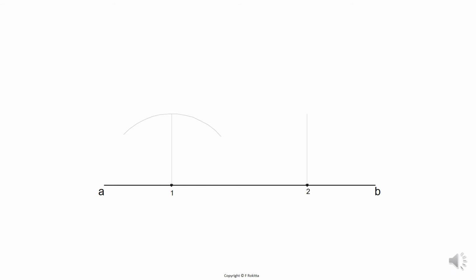The next step is to place your compass then also still stretched at the 30 millimeters as an example and draw another light construction arc onto the second perpendicular line as shown here. Where the perpendicular line and the pinnacle of your arc will meet at both number 1 and 2, that is the touch point of your parallel line that needs to be drawn in, like you will see in the next step.